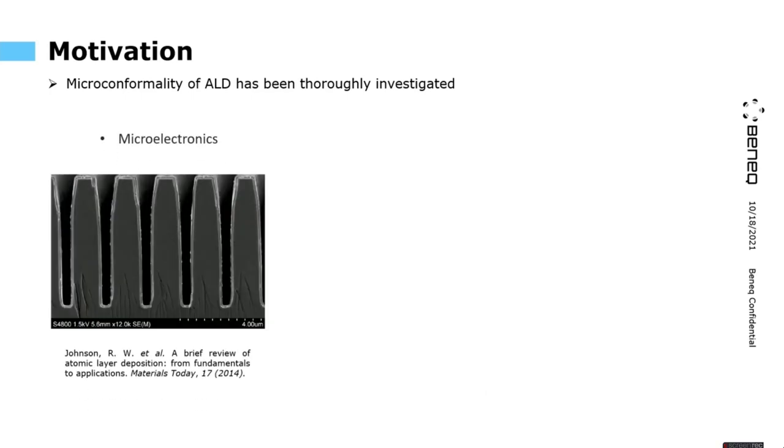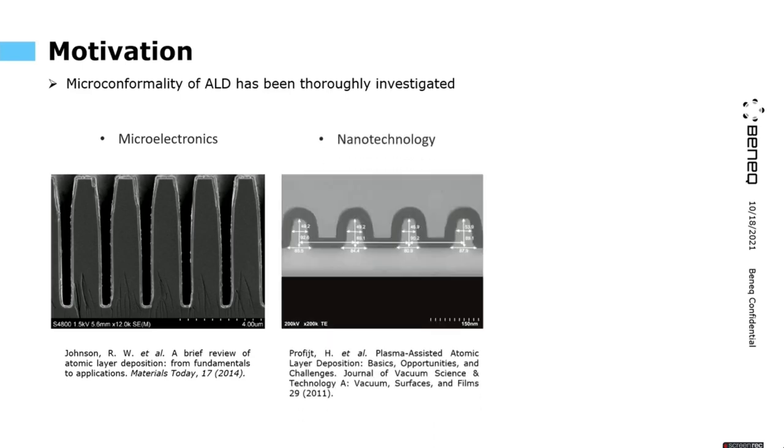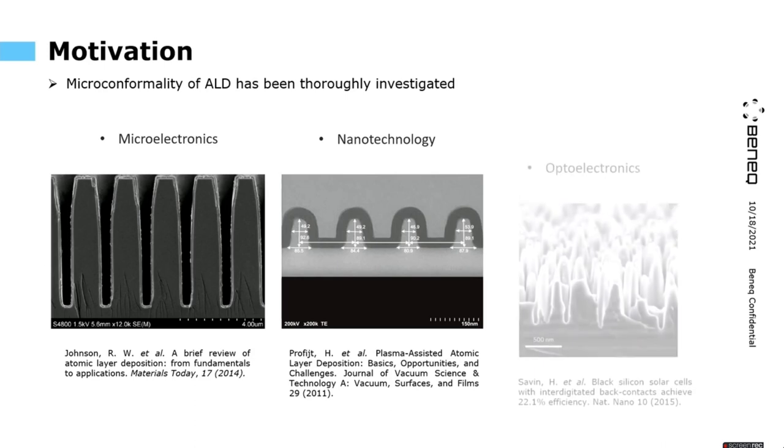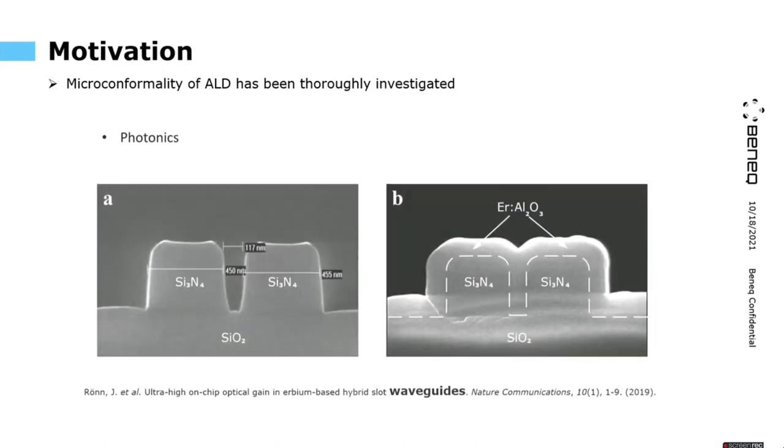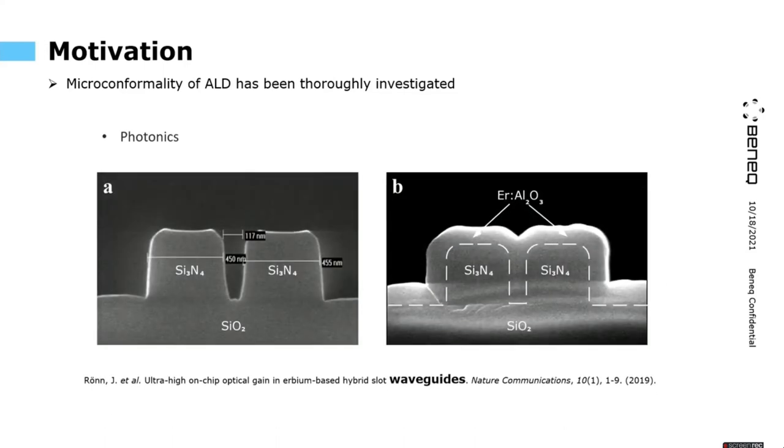ALD has been studied, investigated and used in many types of applications, from microelectronics to various types of nanotechnology applications and optoelectronics. Also in photonics, there's one example of my colleague John Röhn's work on waveguides, where ALD can really accurately be used to control the physical distance in a slot.